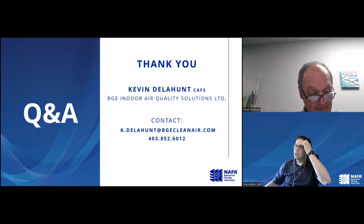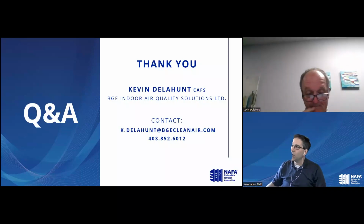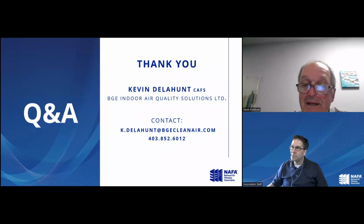So our first question is: are HVAC equipment manufacturers working on making furnaces that can handle pressure drops of filters higher than MERV 14? As far as I know, some of them say they sell HEPA filters, but you would need quite a larger fan than you would with a MERV 6 or MERV 13.